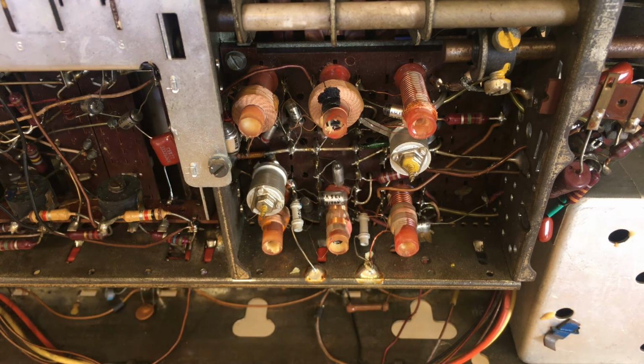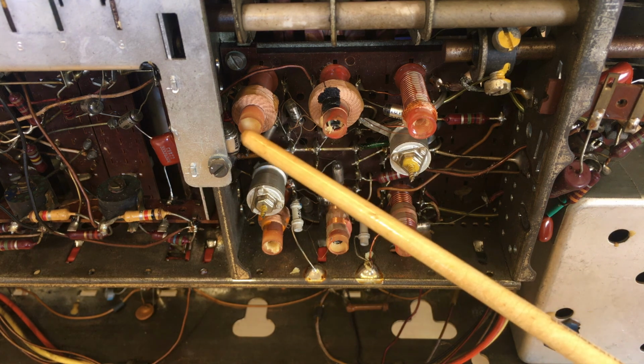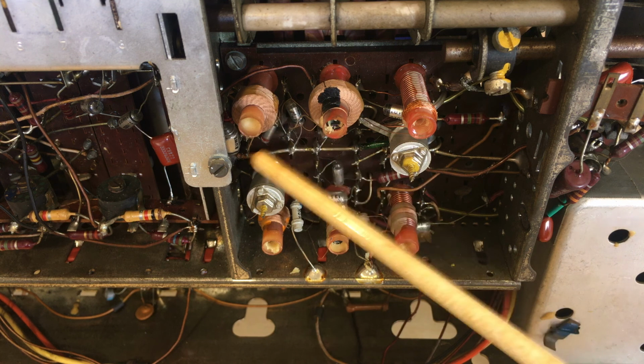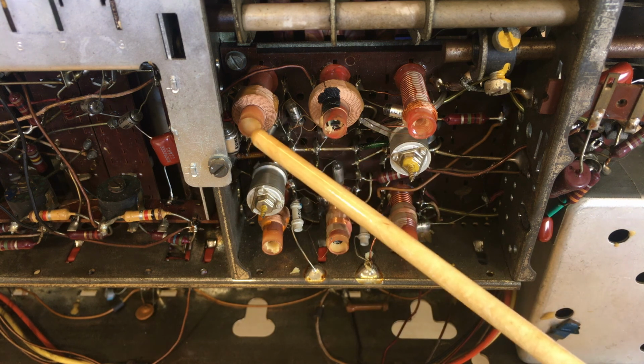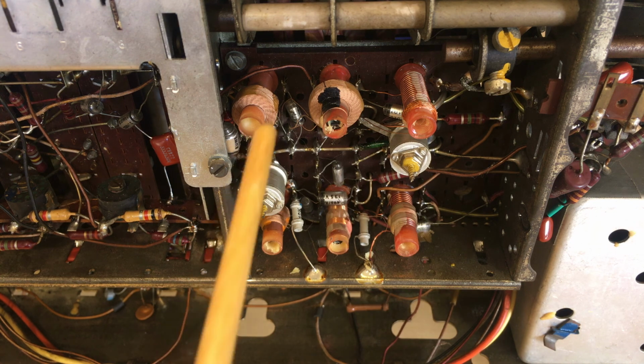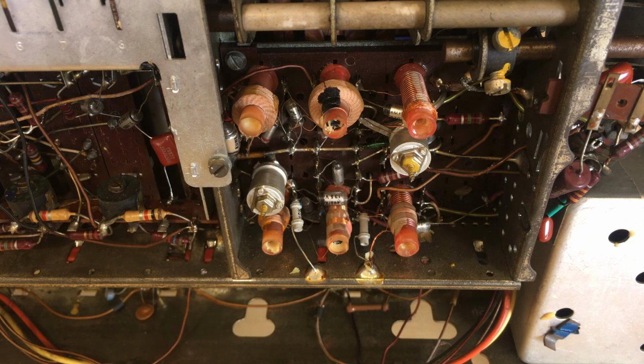The wax on this was not at all messed with. This wax is very fresh. There are no other components really around that. That's straight from the antenna that goes in through that or across that to stop the 460 kilohertz IF frequency. So that one's staying exactly as it is.